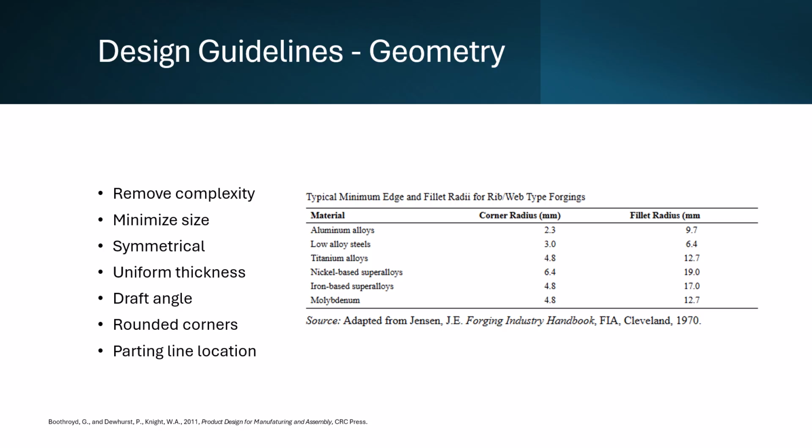The parting line of the die should be kept flat and simple. A cranked parting line can cause mold misalignment and add handling complexity. To avoid this misalignment, die locks need to be added in, which drive up die complexity and weight, both of which increase cost.